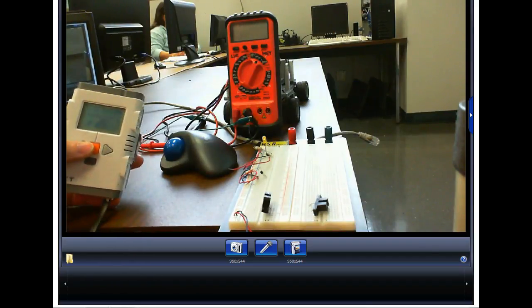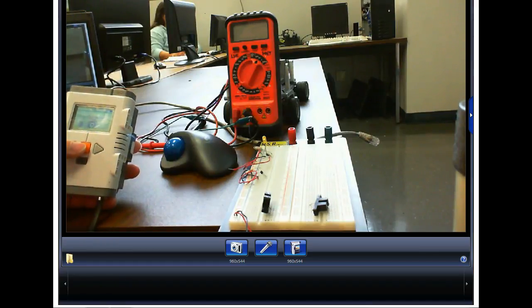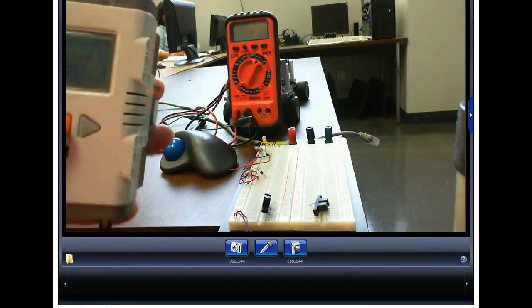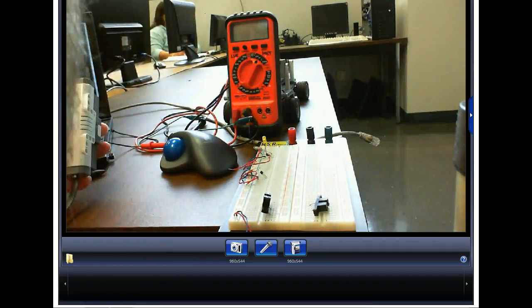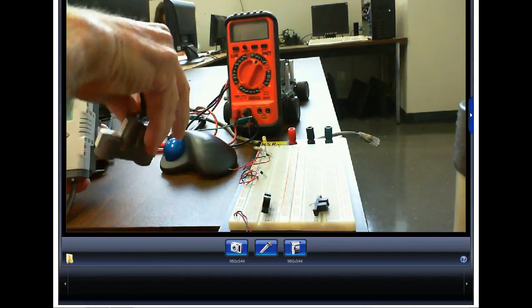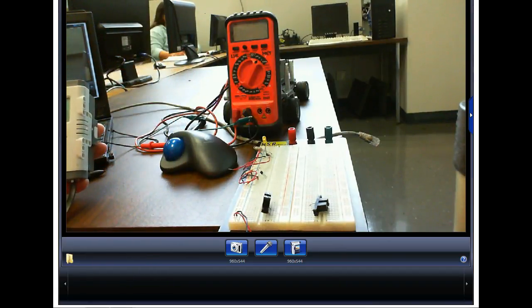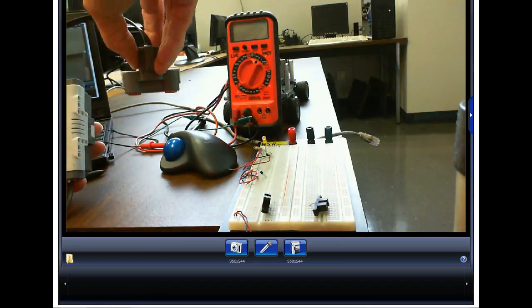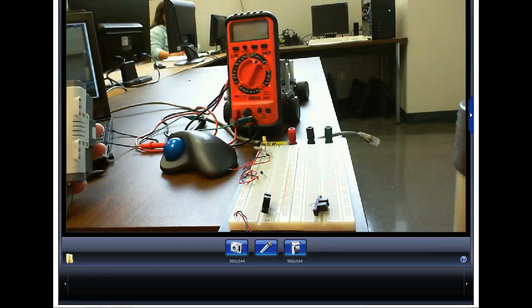So people write a program and they think the sensor's not working when there's an option on the controller to check to see if the sensor's working. I'll show you all how to go through the menus and everything on this, but I'm telling you to check out this ultrasonic sensor. What it's going to do is play a tone. And this is an analog sensor. So what the program's doing is taking this distance and converting it into a tone, right? Can y'all hear it?